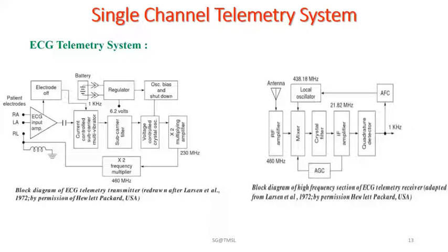On the receiver side, there must be an antenna, which is an omnidirectional quarter wave monopole, mounted vertically over the ground plane of the receiver top cover, and it works well to pick up randomly polarized signals. An RF amplifier should be there.